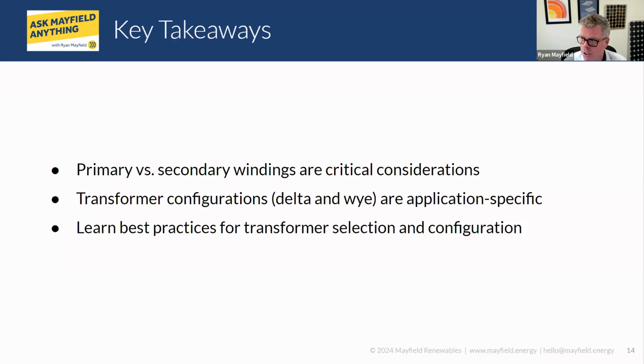Kind of look to the group here if there's anything that you have to say about that one. Yeah, that aligns with what I typically see there. Functionally, inverters might not require the neutral, but I know a lot of them like to see that balanced phase to ground reference. If for whatever reason the inverter doesn't need that balanced phase to ground, you can still use a delta Y transformer and just not utilize the neutral.